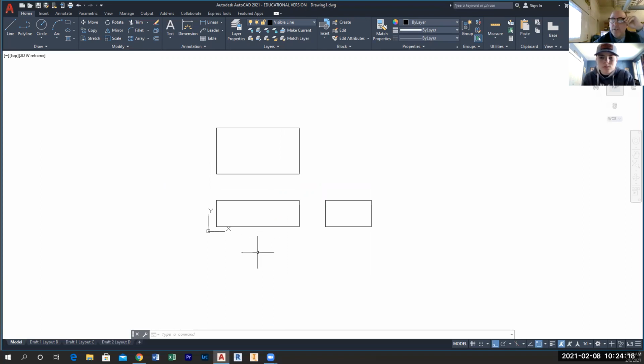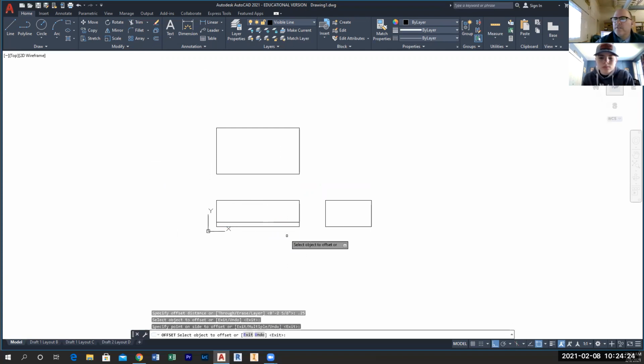It's a 1/4 inch. Let's go offset 0.25. And again, as I do this, there's a feature on the right side view too. That's right there on the right side view too. So this is 0.25 up, and it goes in. How far does it go in? It's actually 3.75. So that's about a 1/2 inch in. So it's 4.75 overall, 3.75 here. So that's a 1/2 inch in.